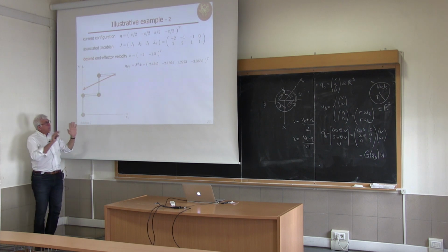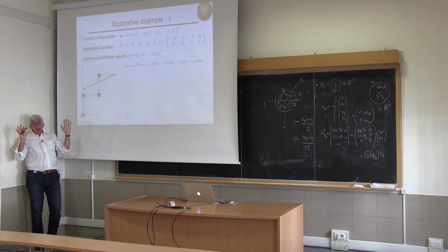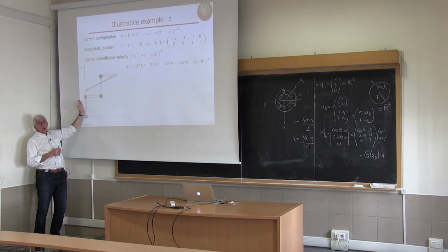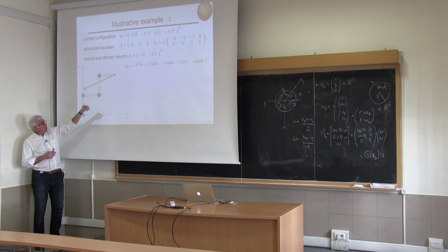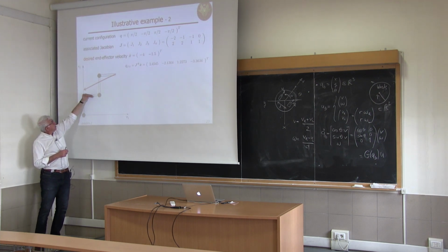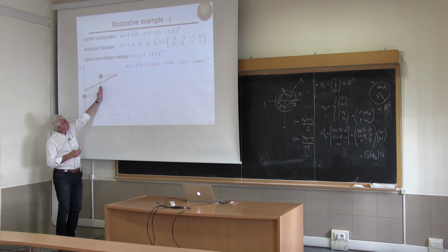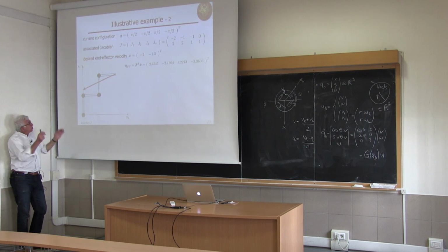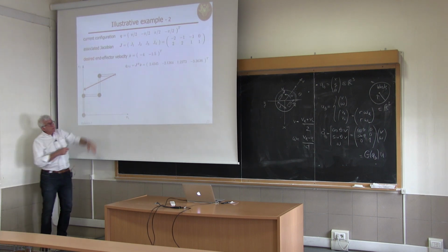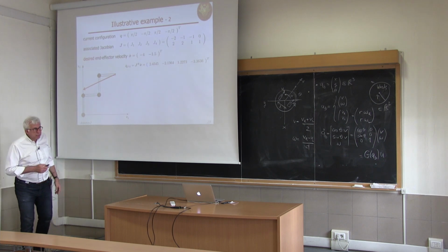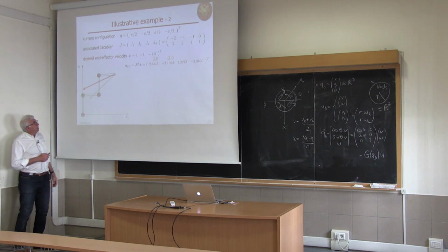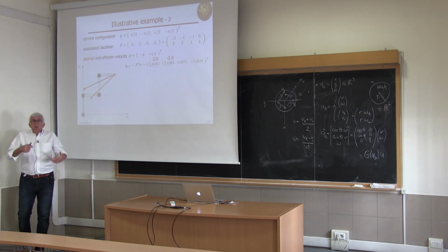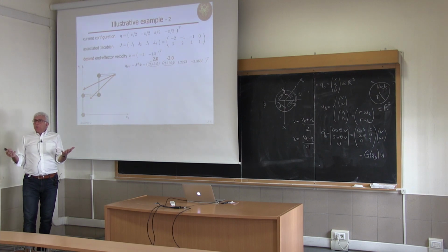And you can see that if we didn't have any hard constraint in the joint space, this would move the first joint counterclockwise, the positive 2.45, the second clockwise, the third counterclockwise, the fourth clockwise, in such a way that the end effector goes in this direction and has the correct speed. But we have limits, and in fact, 2 joints in this case saturate, are overdriven, go beyond what the robot can do.